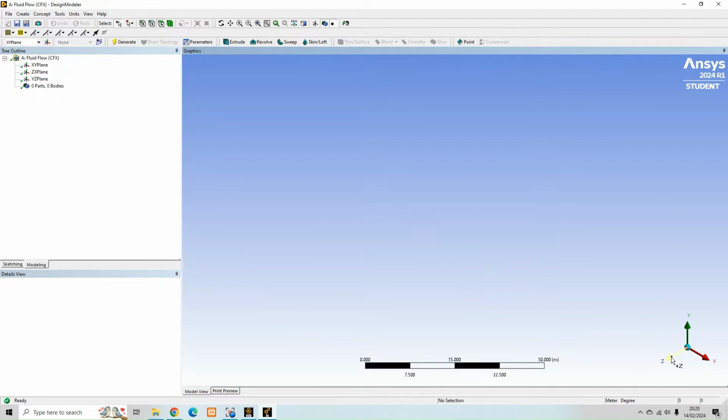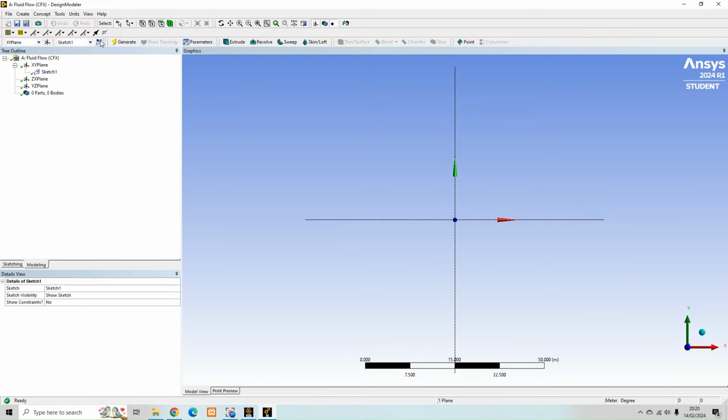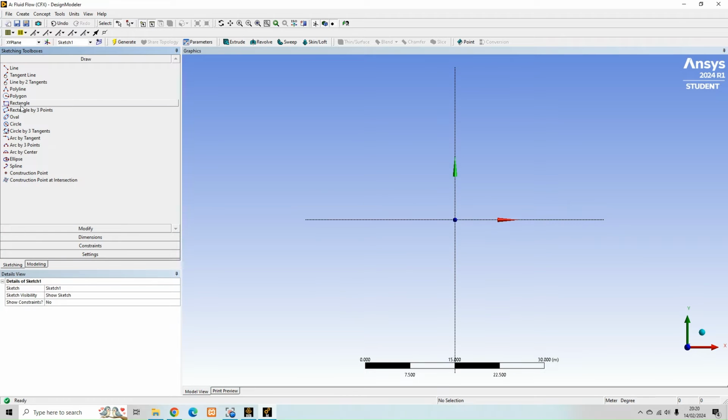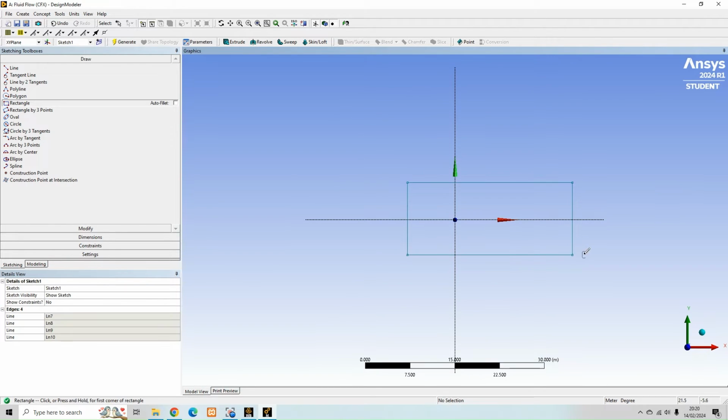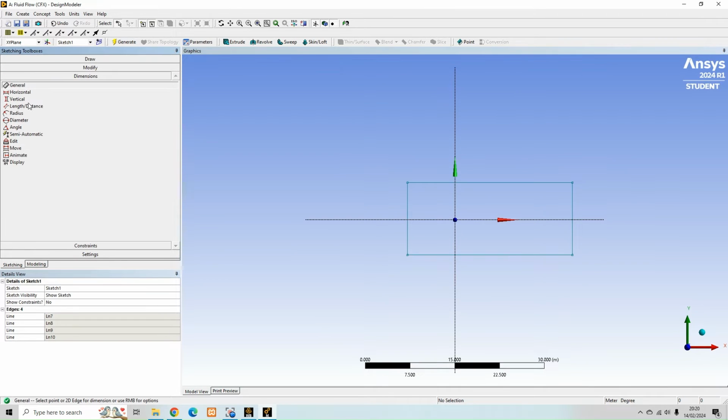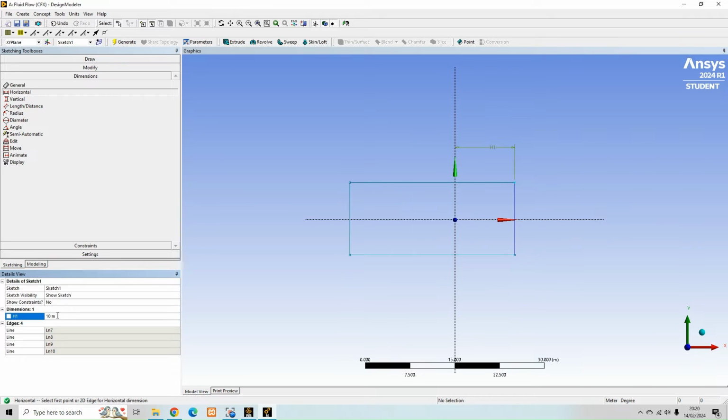So I'm going to sketch my computational domain on the YZ plane. Just bias it slightly downstream so we've got that wake refinement, and I want to place the cube on the origin that you can see there, represented by the blue region. Going to put some approximate dimensions in. So I want the outlet to be about 10 meters downstream. We're going to have a 1 meter cube.